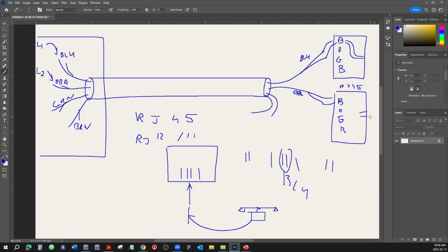I want you to understand that concept. No matter what color, if you're connecting just regular phone lines, one pair for each phone line, it doesn't matter what color the line is using, the jack has to use the blue pair if it's just for the phone. Right? I will ask you that on the test. Not this, well, maybe this one. Who knows? But it will be on the test. But we also are going to reinforce that knowledge by doing a lab, by connecting things a certain way.